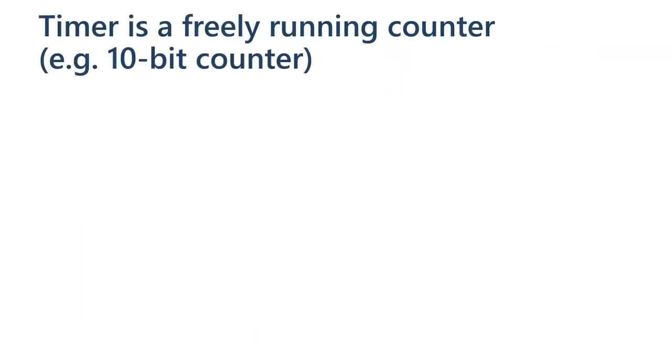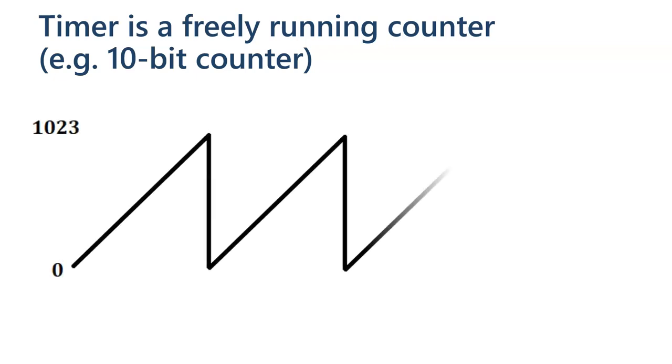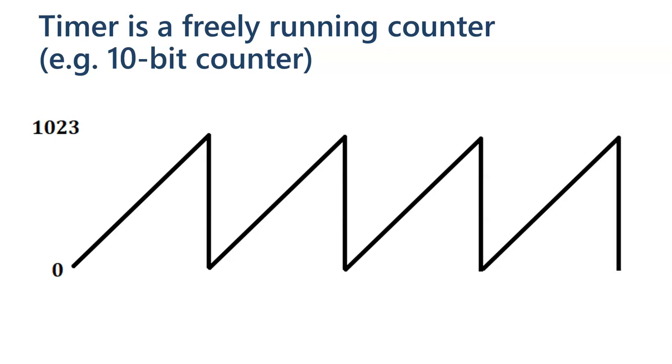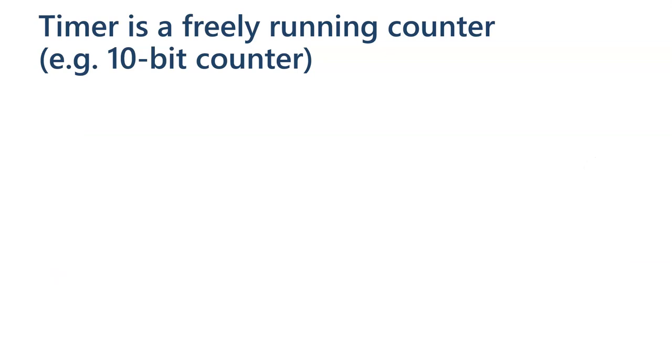So what exactly is a counter? And before we go to output compare, let's take a look at the different modes in which the STM32F4 counters can be set up. So far we've talked about an up counter, and then the count goes to 1023, it resets back to 0, right? This was an example, 1023 only because here I said the example is for a 10-bit counter. Going up to 1023, resetting to 0, starting count up again, 1023, and so forth.